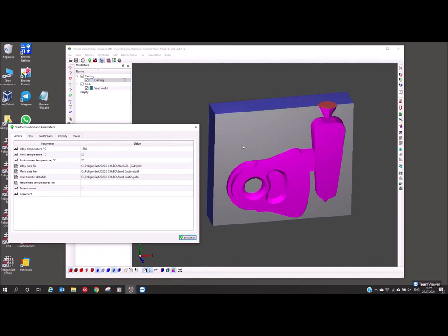It's a very fast case setup because I don't need to select some of these interfaces and set up these coefficients and so on. Most things will be made automatically. So what data can we set up here? Thread count. You can use all CPU cores. If you have AMD, for example, with 8 cores, you can select 8 cores here. My Intel Core i7 has only 4 cores, so I will set up 4 cores.